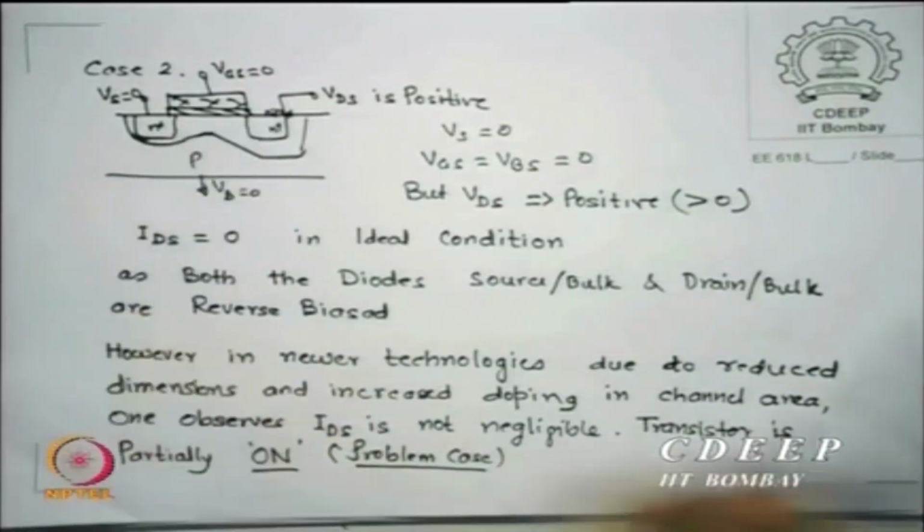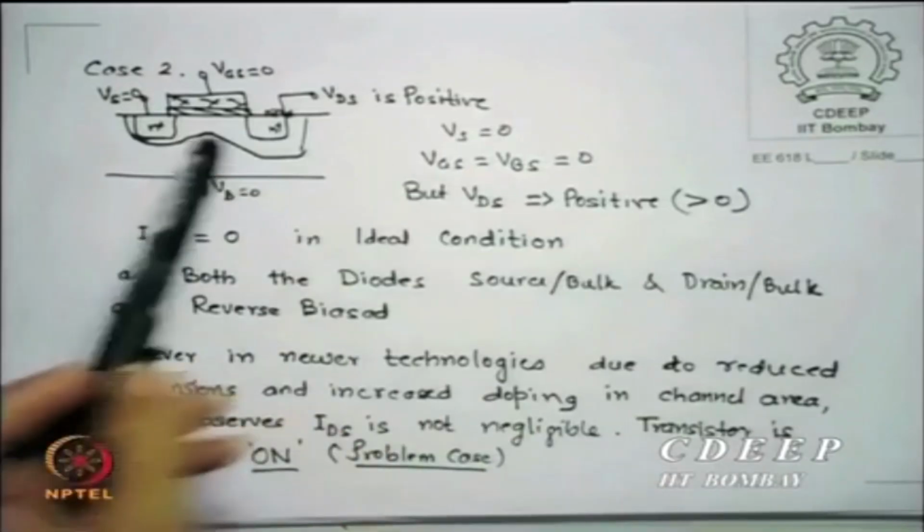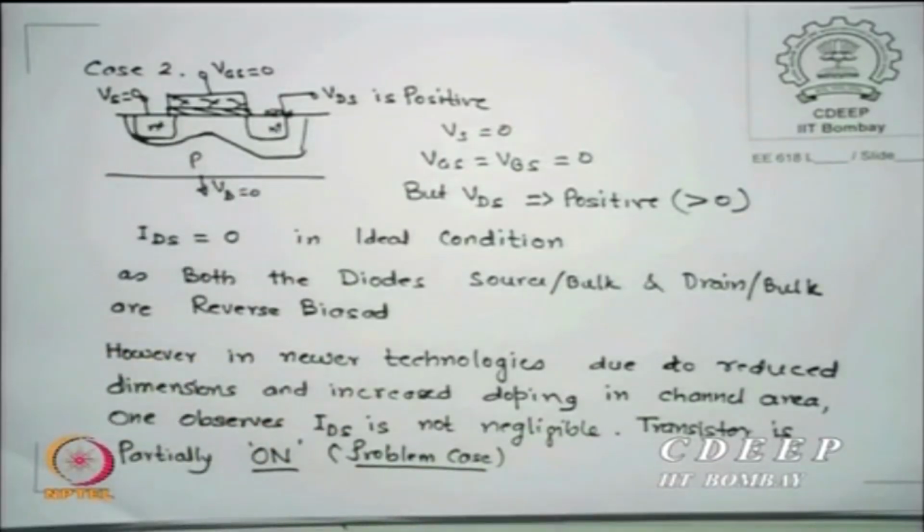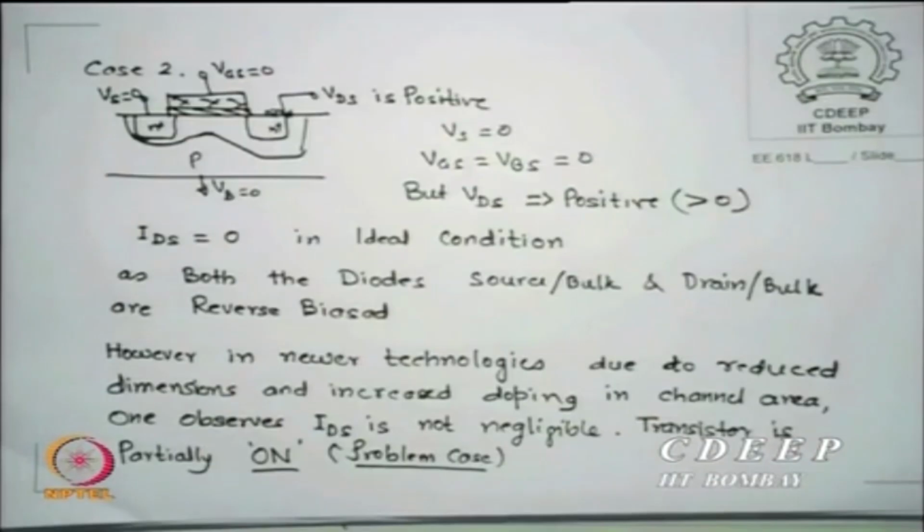Since they are giving reverse saturation currents, there will be a current from source to drain which is called the leakage current. The off state is always normally recognized when VGS is 0, we say when VGS input is 0 no current, we say off, but in this case VGS was 0 but some finite current, maybe very small, picoamps sometimes or nanoamps, okay. In the present case it is becoming tens of hundreds of nanoamps reaching microamps now, that is our worry now in 11 nanometers, 16 nanometers.